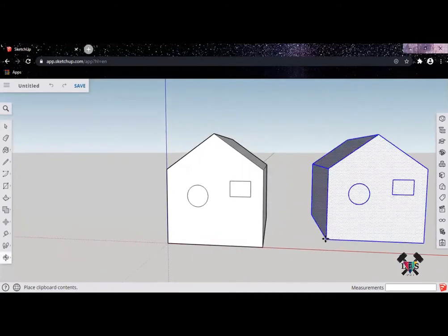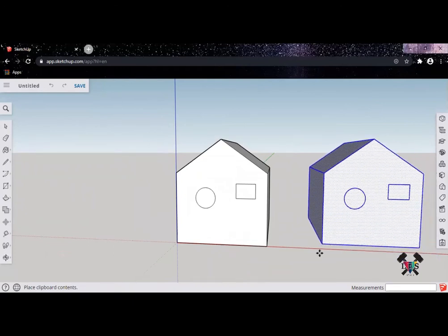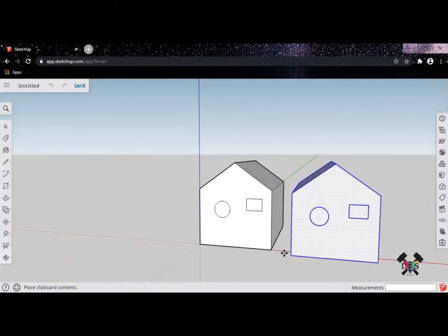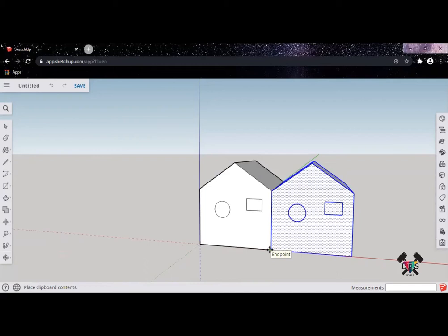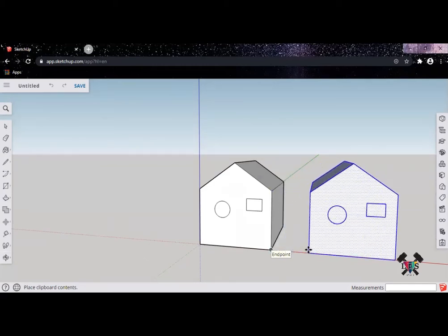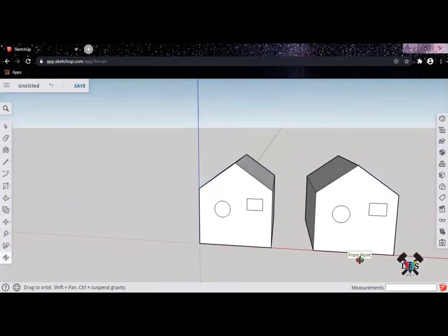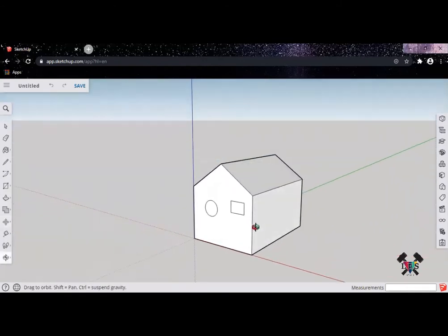Sometimes it's kind of difficult to make sure where it really is on the plane. It can be down or up and stuff, so it's very free. What you could do is line it up with a point that you want it on. Let's say you wanted it parallel to this, line it up to that, and then slowly move it towards the red axis. And then you'll notice it's just perfectly aligned. Let's get rid of that.